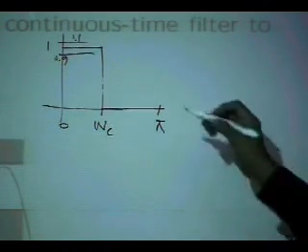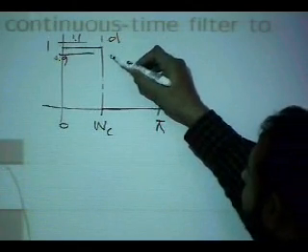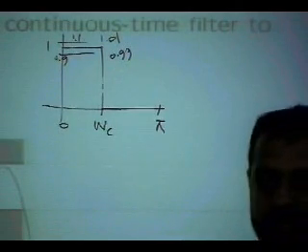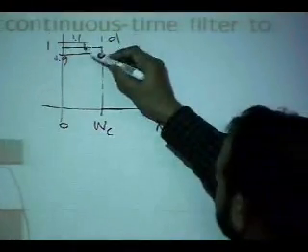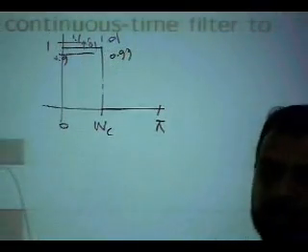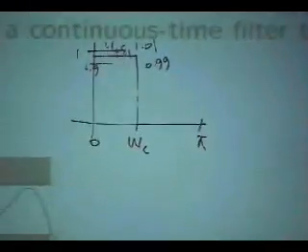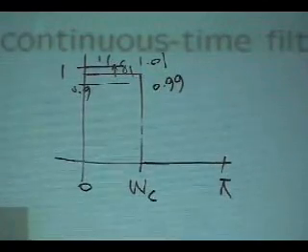So you may say, I want it to be 1.01 and 0.99. You can give specification in terms of this delta 1. It can go above or below 1 by delta 1, and as you keep tightening this, the filter will start getting more and more complex.